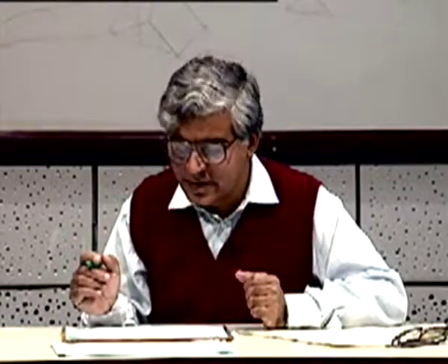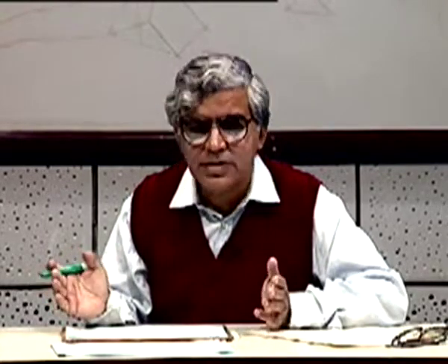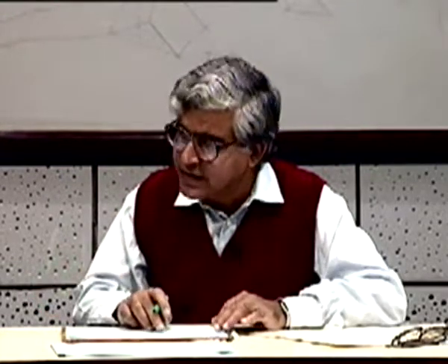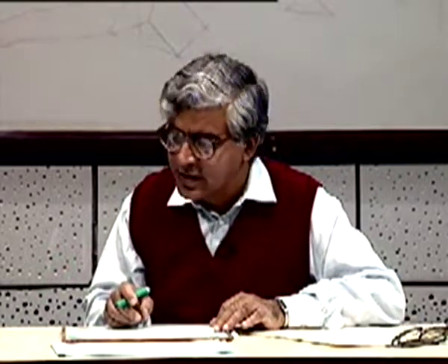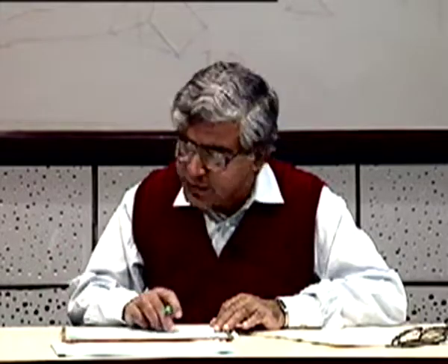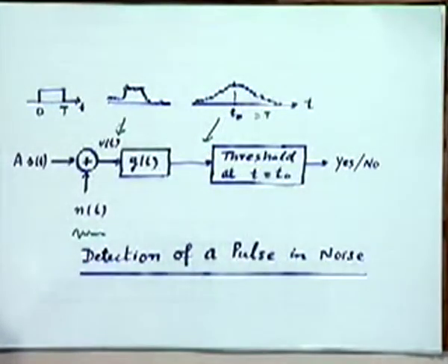Basically, intuitively, something similar to what we discussed a long time ago, the idea is to reject noise. One way of rejecting noise would be to integrate it out, right? No, we are not really doing integration here, we are doing something more general than integration. Integration is a very special kind of operation. We are not putting any constraint on what that operation should be. We are allowing the filter to be as general as possible, right? Integration will turn out to be a very special operation, but roughly yes, you can see it from that point of view, that you want to integrate the noise out over the symbol duration, over the pulse duration.